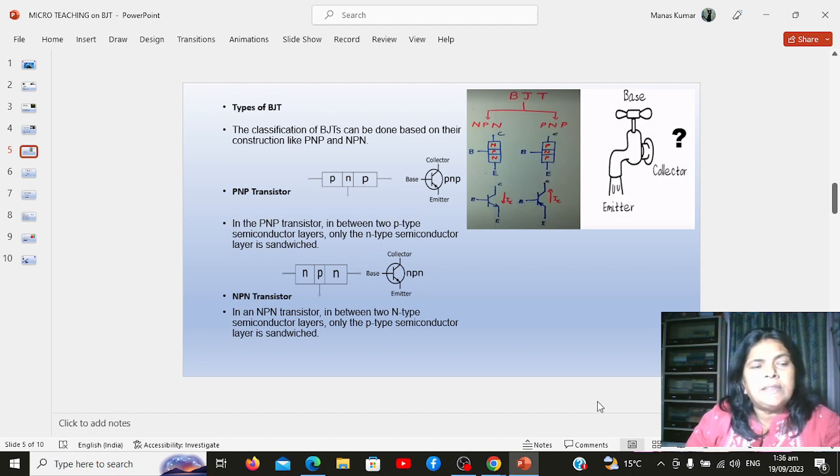The two terminals, emitter and collector, are taken out from the two N-type semiconductors and the base terminal is from the P-type semiconductor. In the BJT symbol, the arrow on the emitter terminal indicates the direction of conventional current in the emitter with forward bias. For an NPN transistor, the conventional current flows out of the emitter as indicated by the outgoing arrow.